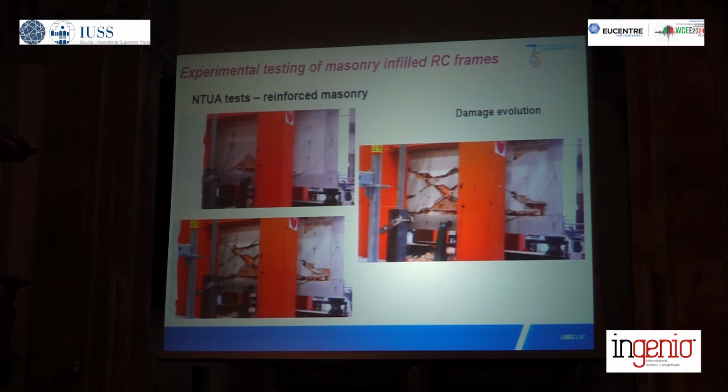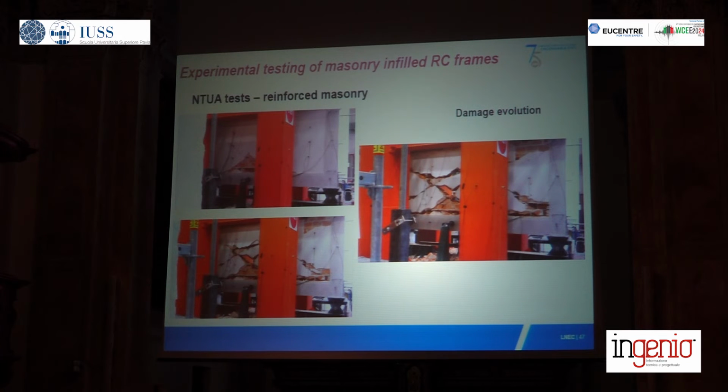And so if you look at some videos of test results, the upper left is a lower stage, the lower left is an intermediate stage, and on the right you have the final stage, which is actually more advanced now in the video, but you will see the others moving soon. Okay, and so you see, for instance, at the very final stage, that the cracks are very wide. You have huge damage on the infill, but it is still not collapsing in the out-of-plane direction because of the bed joint reinforcement.